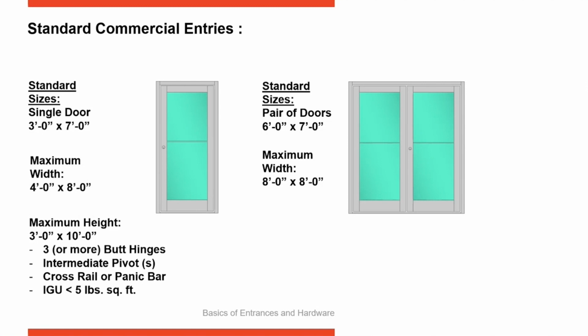Most commercial doors have a range of infill from 1/4-inch glazing up to 1 inch, and that can be accommodated very easily by changing the stop. You can see the stops on these doors push into a raceway and snap in place. So to change the infill, we're basically just going to vary the stops being used.